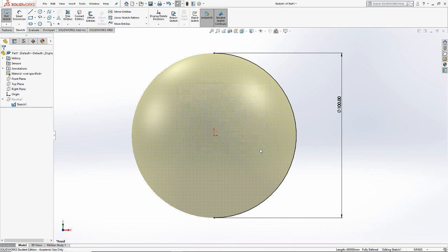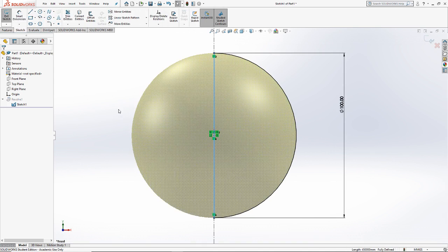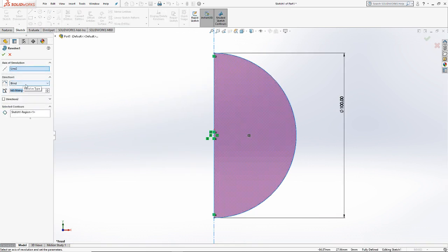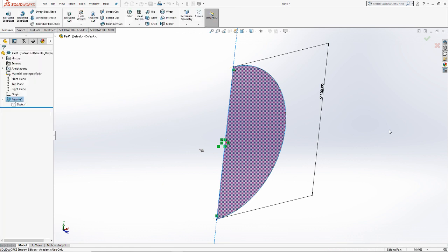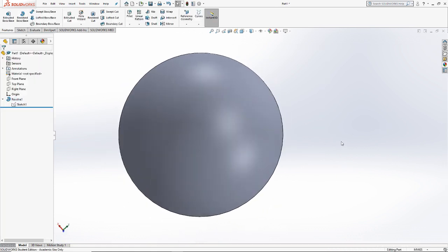Another mistake that you may have made if you are approaching this for the first time is how far to extrude. So in my revolved extrusions, I have it set to extrude in one direction, 360 degrees. By default, SolidWorks sometimes pre-populates to 180 degrees, which creates half a sphere, which if we had created an entire circle on the front plane would actually work out just fine.